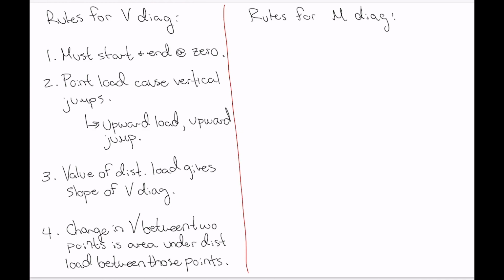Now, in terms of the rules for drawing the moment diagram, there are also 4. And the first rule for drawing a moment diagram is that the moment diagram must start and end at 0.